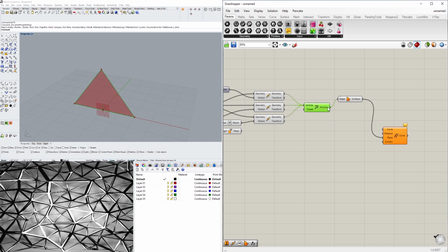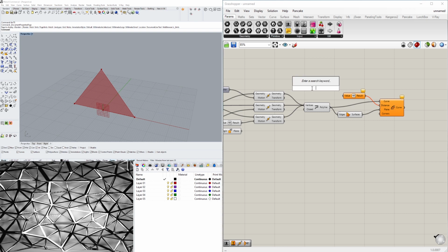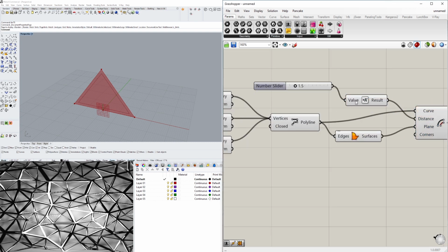Then we can use the polyline as our curve, so it'll reference this surface as our plane, and it's offsetting to the outside, so we can either flip the direction of the polyline here, or we could just go to negative component, and we'll use a negative value for the distance. So let's go here to 1.5. So that's 1.5 feet.